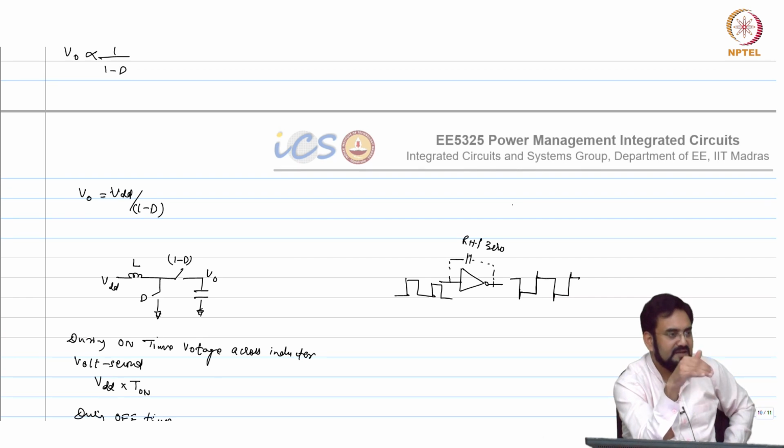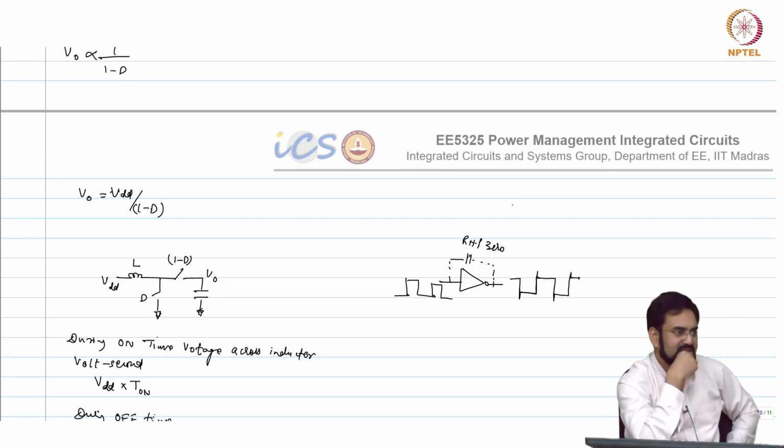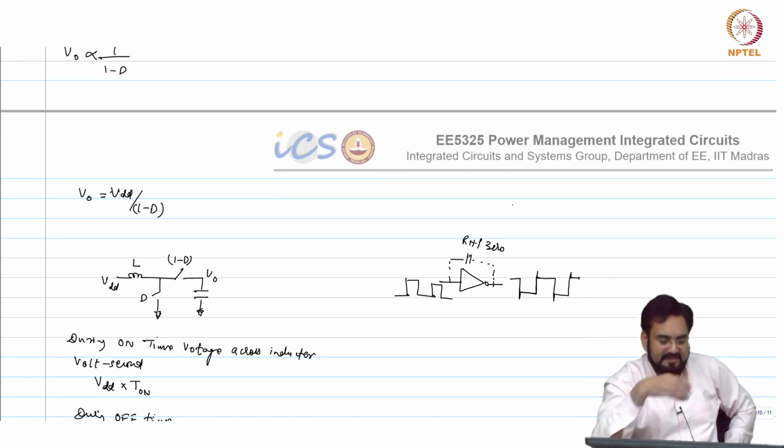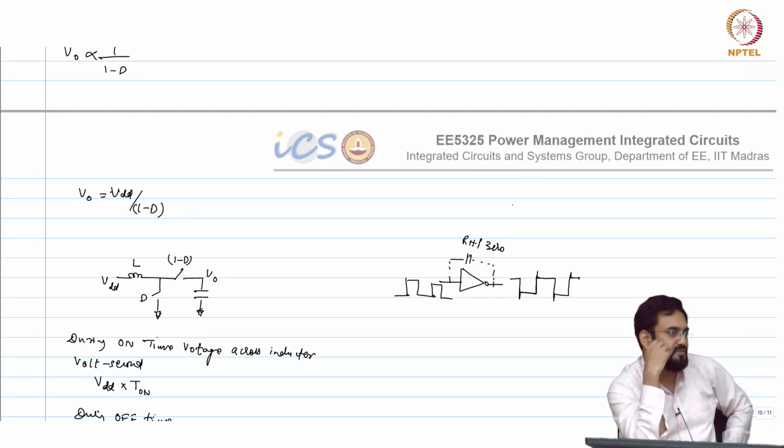Let's say I am operating at 5 volt. Now I want to bring it to 10 volt by simply changing the reference voltage. Let's say my reference was 0.6 volt. At 0.6 volt, my output was 5 volt. Now I make it a 1.2 volt reference. I should expect a 2x output, which is 10 volt. So I simply give the step, it should follow the step, but it will look like what you are seeing in the inverter, because it has a right half plane 0. But intuitively, if you want to explain, how will you?